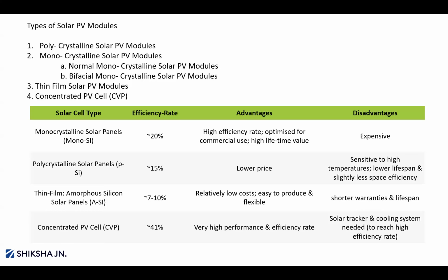Because monocrystalline modules are higher efficiency, but earlier, whoever manufactured them made them only for low temperatures, like in Germany and the US. In those markets only monocrystalline modules were used because there you can get higher efficiency. If we used them in India at that time, we could only get efficiency equal to poly.